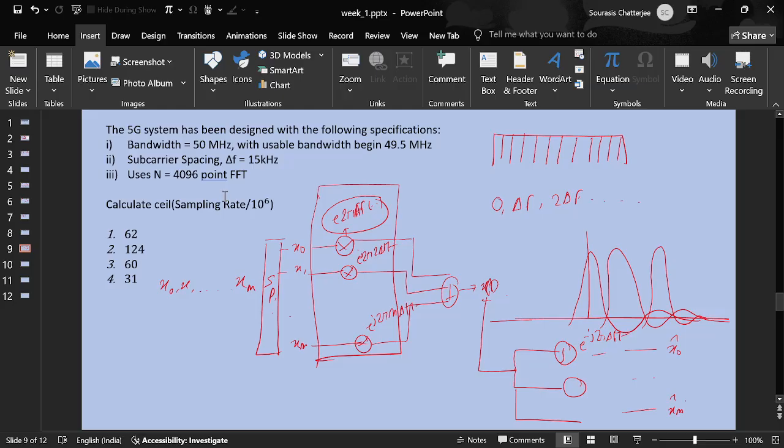So your positive bandwidth is 25, right? 0 to 25, and twice of that is 50, right? Or am I getting it wrong here? Yes, no, I'm just asking. Okay, so my sampling rate should be more than 50 megahertz. That is confirmed. Okay. So what next?